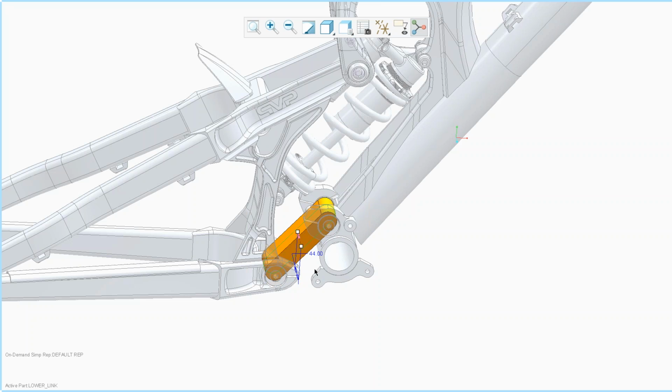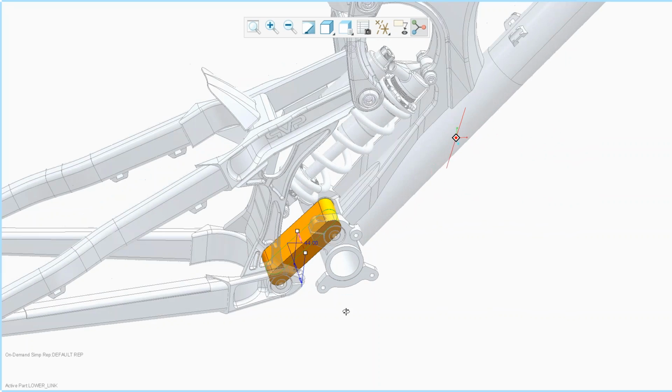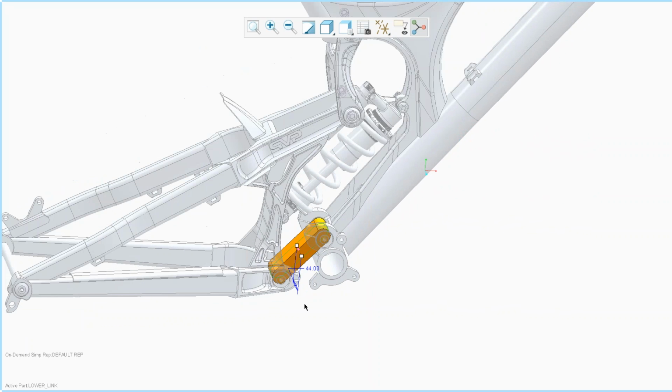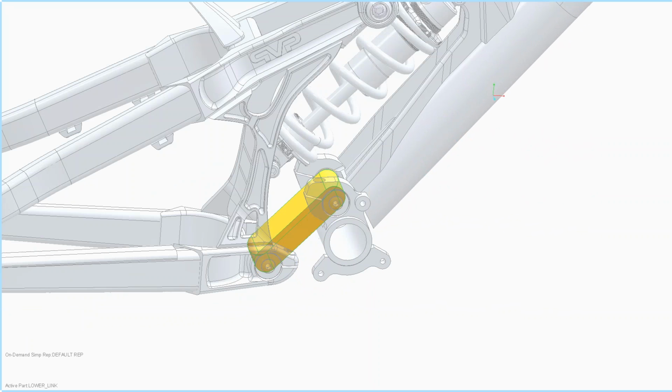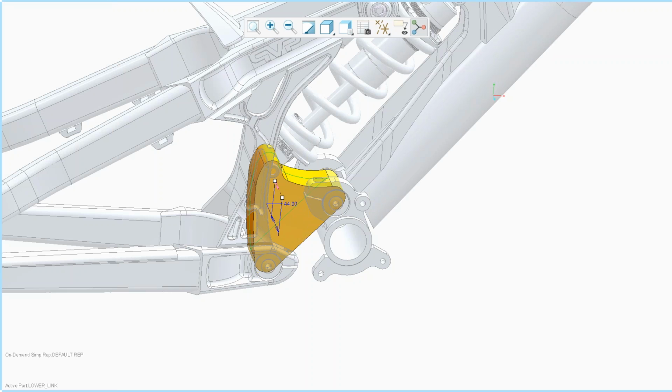So let's say I had a very simple piece that I'm creating to connect these two assemblies in the frame assembly, the bike frame assembly. Now, having done that, I could do a Control-C, Control-V. What is that? Copy-pasting the same feature again. Why did I do that? Because I know when I copy-paste, I could copy-paste this with a different sketch.